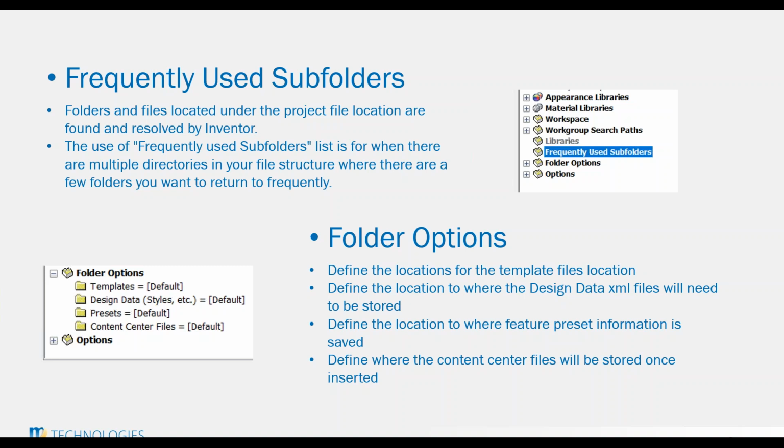But again, it's something you might want to play around with. It's anything that comes up in the properties dialog box of the feature. In other words, if you go into tube and pipe, there's a properties palette there. If you have all these tube and pipe styles, you can save those. Hole settings, you can save those. Again, there's a lot of preset information being generated there.